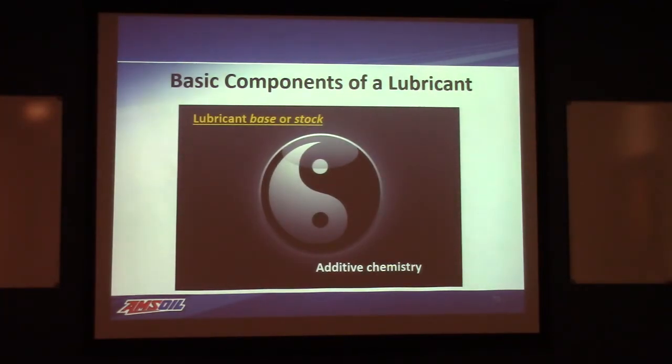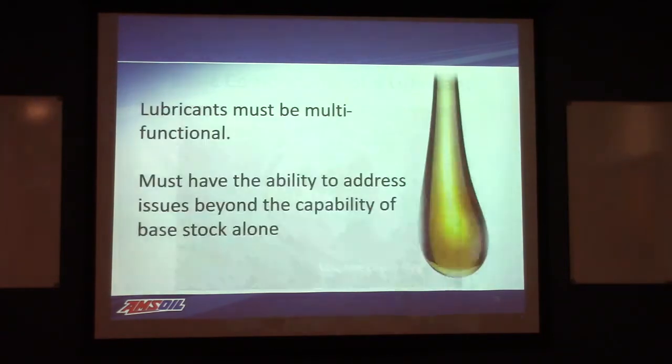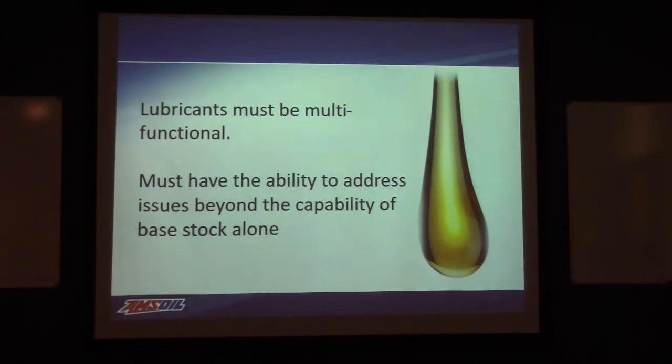Virtually all fluid lubricants out there are a combination of base fluid, base stock, whatever you want to call it, and some type of additive chemistry. And the reason, again, is because lubricants have to be multifunctional. Certainly wear is an issue. It's a major concern. But there's a lot of other things that are of concern also.